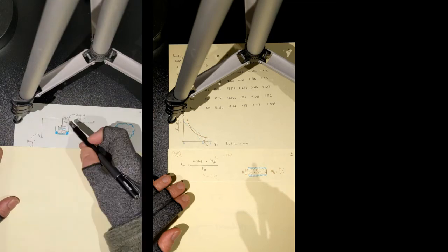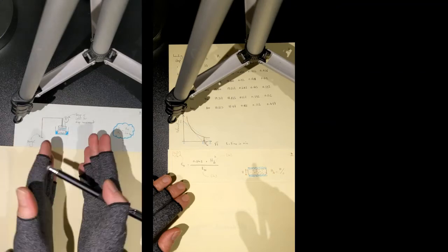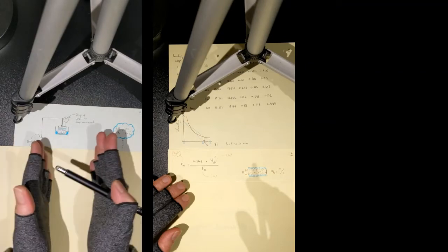This is really the general layout of your oedometer test, or one-dimensional oedometer test, one-dimensional consolidation test. Your test is one-dimensional because the soil is confined in a rigid ring. It means that the soil cannot show any form of displacement laterally. The only displacement that it can experience is axially.